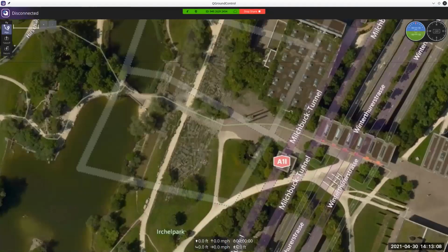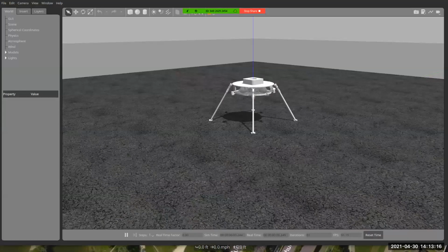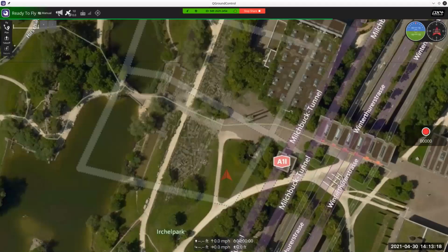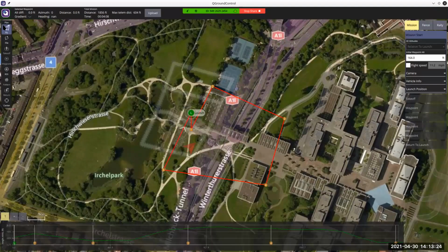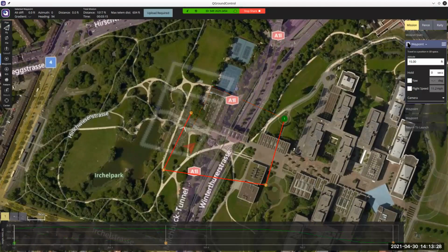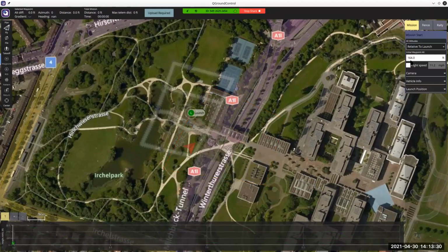Just while you're doing this, to clarify, and either Andrew or Jose can correct me: you set up the simulation environment, and QGroundControl provides an opportunity for you to create a simple profile for the vehicle to fly or execute, but the guidance algorithms are actually embedded inside the PX4.